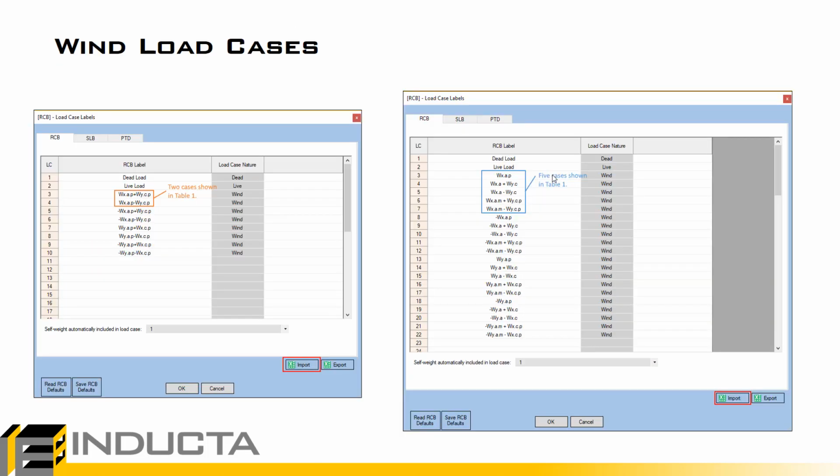So going to the next slide, this is what the orange peak wind cases look like. So considering all directions, we have 8 total. These reduced ones, the blue ones, these are the ones that we saw. Then we have an additional 3 sets for the other along wind directions. Now, don't be alarmed, you don't have to type this in manually. If you go to the manual, to the wind section, where you see these figures, we have download links for Excel files for these tables, which you can then import by pressing the import button.